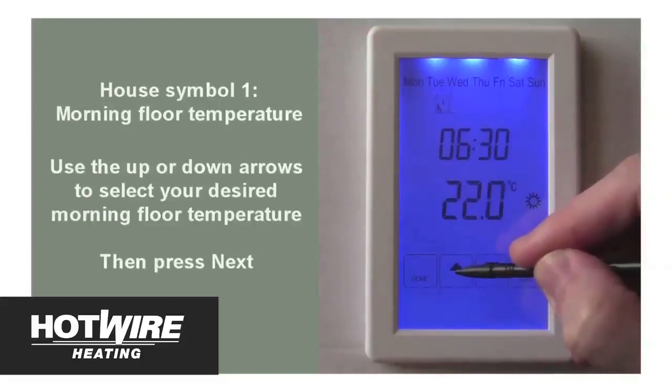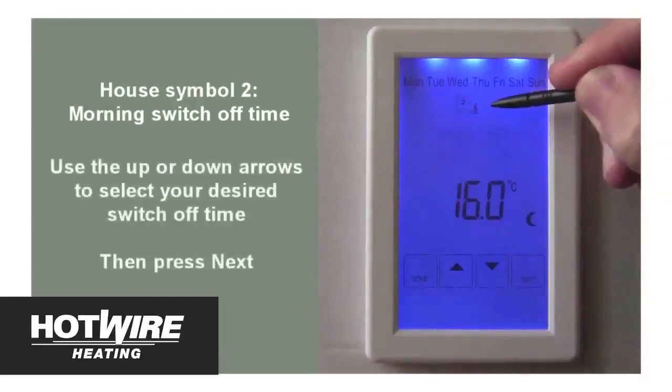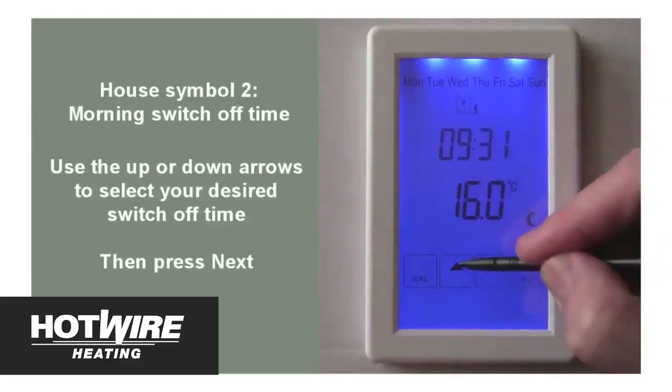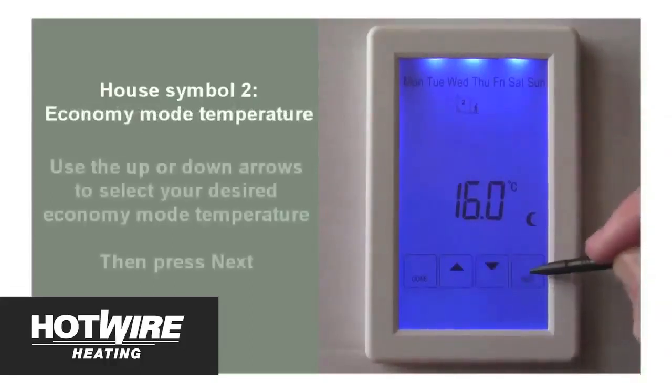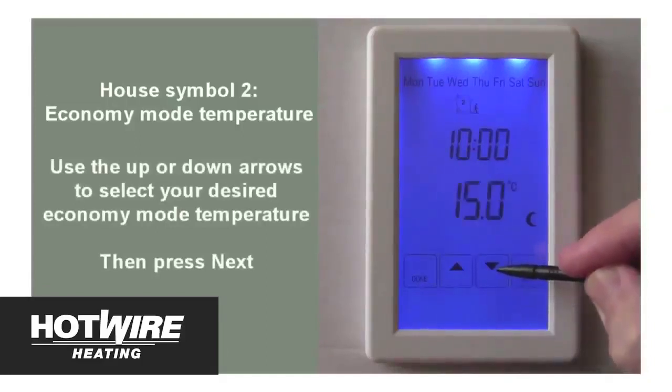Then press Next. The house symbol displaying the number 2 and a person leaving will show at the top of the display. This is your floor's morning switch off time, whereby your floors will cool down again to their minimum or economy mode temperatures. In this case, we will have the floors turn off at 10 o'clock in the morning. Then press Next to select your minimum or economy mode temperature. In this case, 14 degrees.